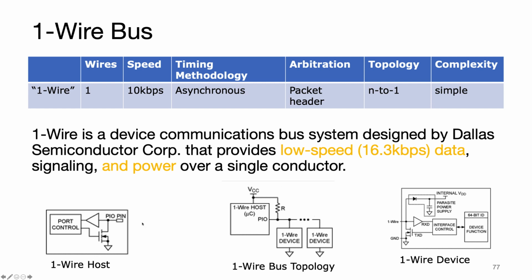The way this works is it's just like I2C plus UART, in the sense that, remember in UART, you had the start bit where it was always a defined line, and you had to oversample the start bit and figure out where the middle was, and then use that for the rest of the timing.